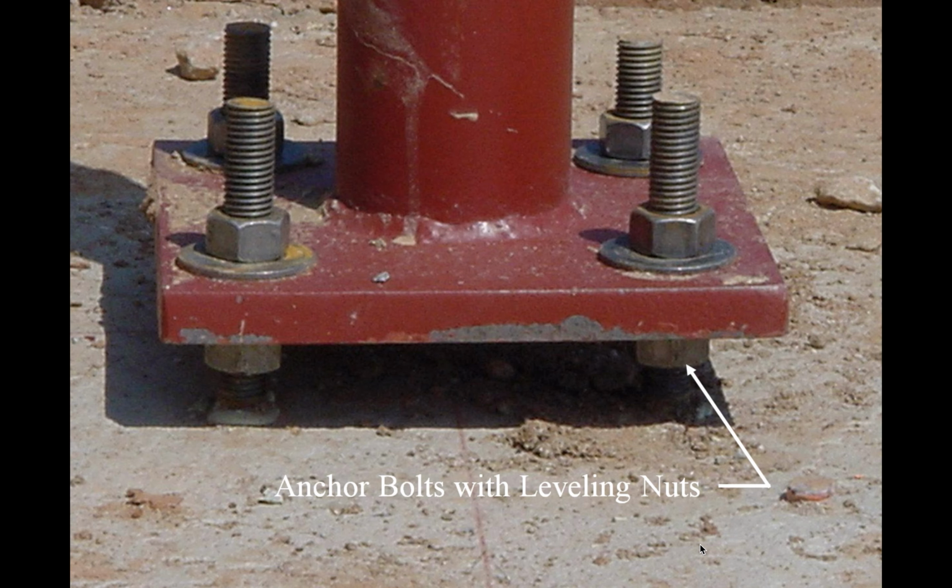You use survey to make sure that your base plate is plumb, and then generally underneath that steel comes a layer of grout or more concrete to fill that in. So the surface of the steel does touch concrete or grout, and you have the bolting in there as well to support it.